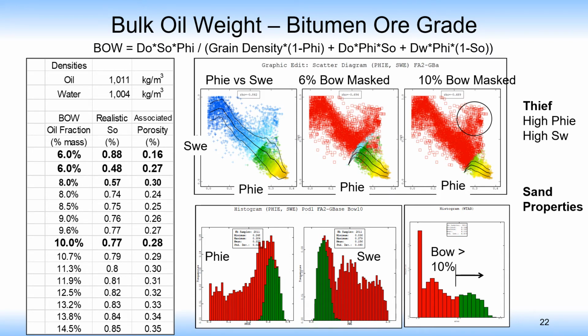In mining, they use 7% as a cutoff for the blending to go into the processing plants. 7 is usually the bad that is sometimes avoided depending on the clays. But in our oil sands, we look at it at 6% because we're targeting this 50% water as our thief zone. So here it's 48% oil, that'd be 52% water, and that's a 27% porosity, gives you 6%.